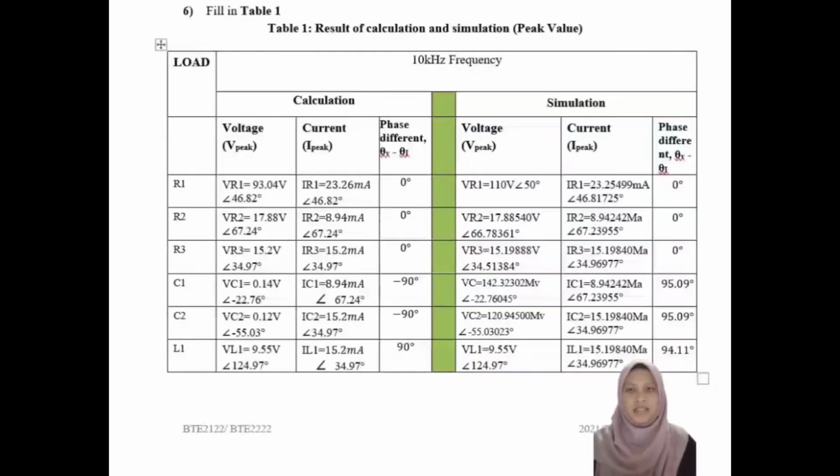In an RLC series circuit, when the AC voltage supply is applied, the resulting current I flowing through each component will remain the same. Thus, the voltage drop across each component will be, for resistor R, VR equal to IR, in phase with the current. For voltage across inductance L, VL equal to I XL, it leads the current by the angle of 90 degree. And for the capacitor C, it lags the current by 90 degree. The total voltage across the circuit is not just the algebraic sum of the voltage drops across each component, but the vector sum.